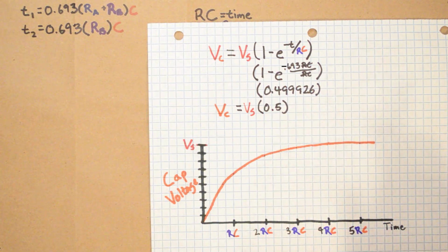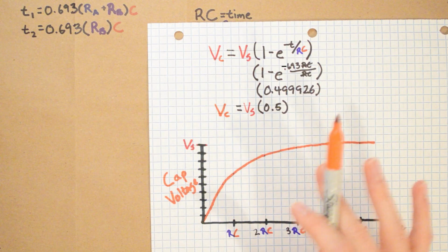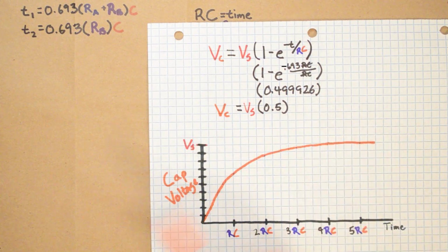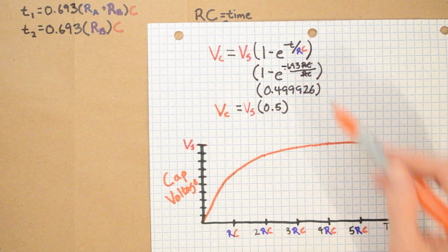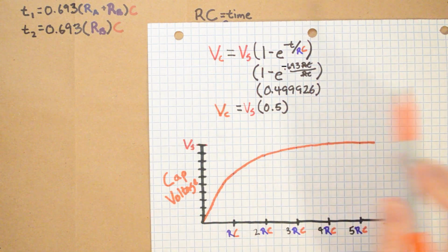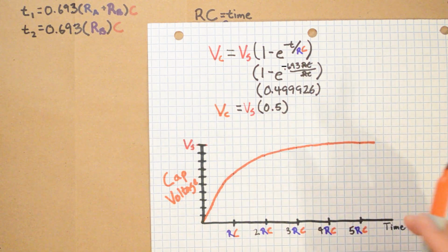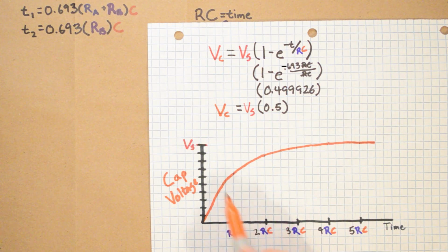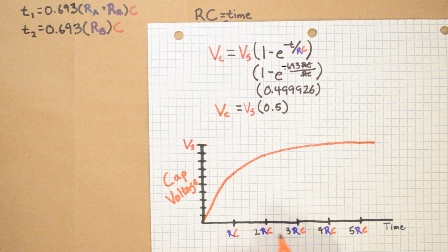First, let's address the initial charge. As soon as you turn the 555 timer on, the capacitor is going to charge up from 0 to 2/3 of the voltage source. We're not going to count that, because it's just the initial charge-up, and after that it's going to go from 2/3 to 1/3, 2/3 to 1/3, 2/3 to 1/3. The initial charge just happens once and never happens again. It takes however long it takes to reach 2/3 of the voltage source, probably somewhere between 1 and 2 RC.